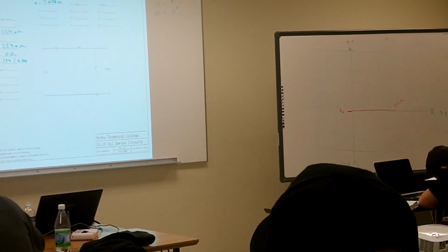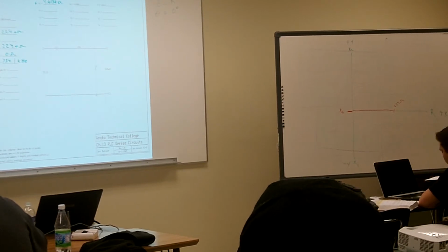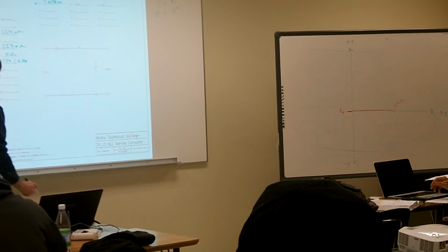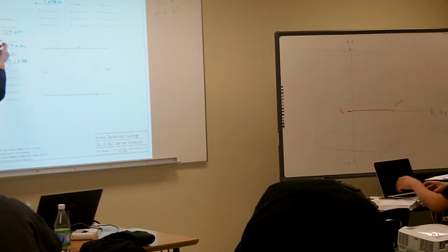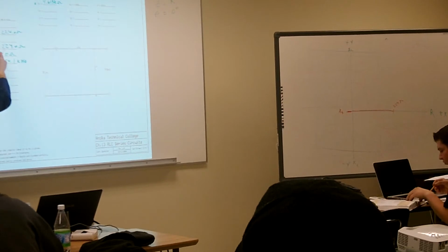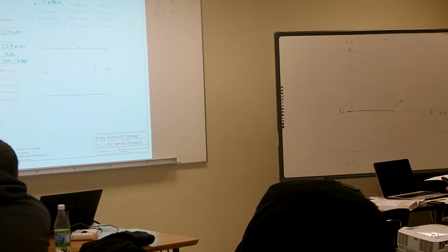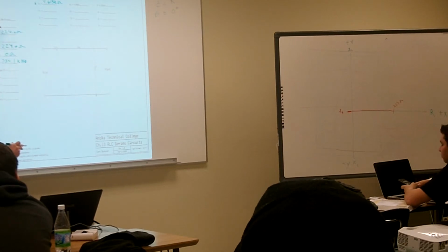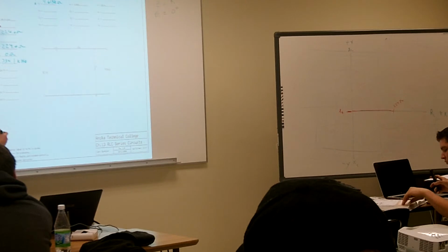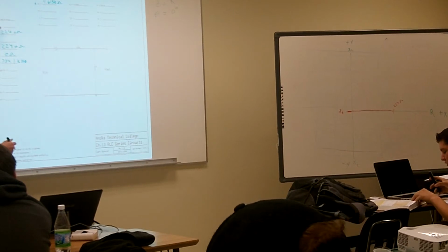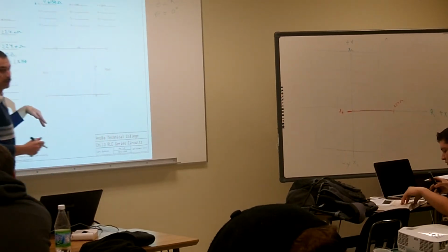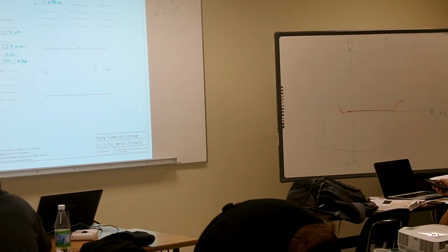All right, so now let's figure out some of our other voltages going across here. We have enough information that we can use Ohm's law, or we can also do our rectangular to polar function. Either one. But let's stick with what we know. What remains constant in a series circuit? Current. So that would be the next thing I would do. I would take care of my current, because once I figure out the current, I have my current going through the whole circuit. So figure out what your current is going through the circuit.